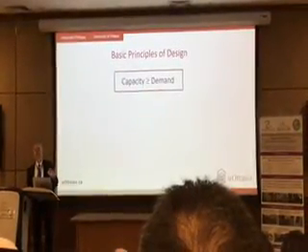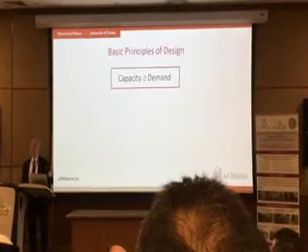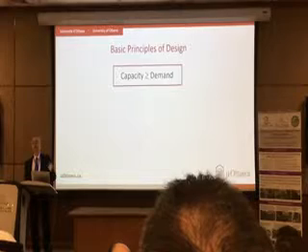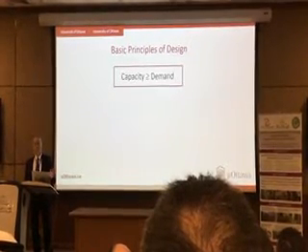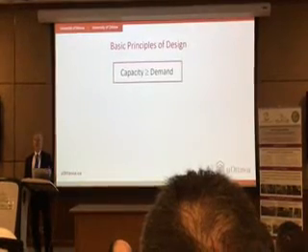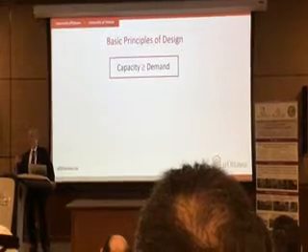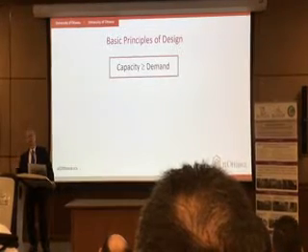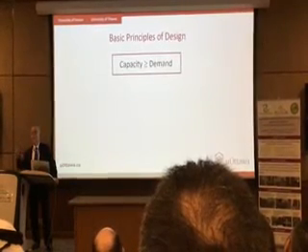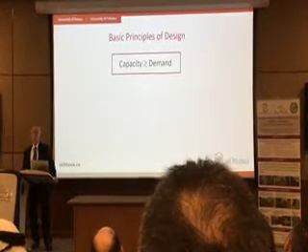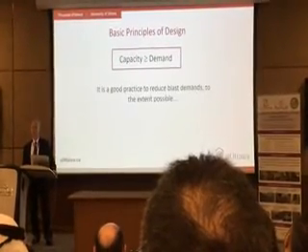As you know, when we deal with extreme events, resisting the extreme event is one factor, and dissipation of energy is another factor, which means to dissipate energy, you have to have inelastic displacements. The area under the force displacement relationship is energy consumed, energy dissipated. So ductility becomes important. Nonlinear behavior of materials comes to the forefront, and that's why we have to talk about force capacity and deformation capacity and compare it with demand.